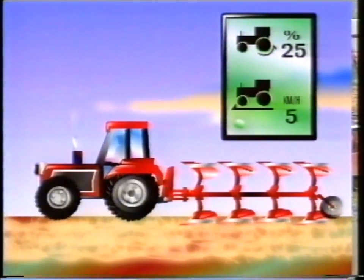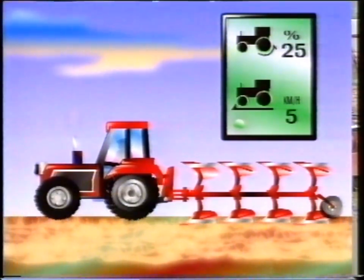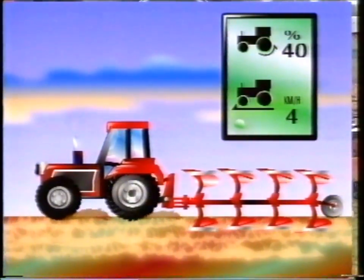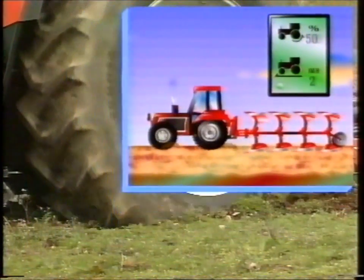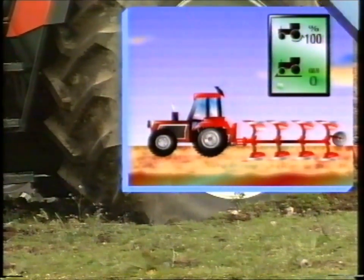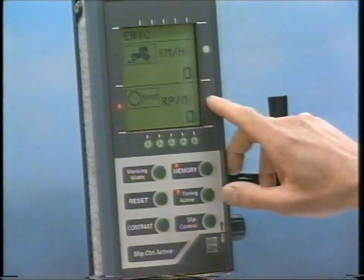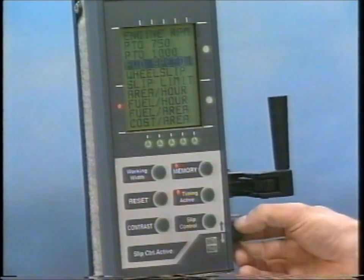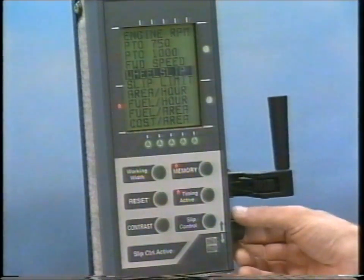First of all, we need to understand the dynamics of wheel slip. If left uncontrolled, wheel slip caused by a loss of grip reduces forward speed, thus reducing the draft force imposed by the implement on the tractor. In an effort to maintain the draft force, the ELC will instruct the linkage to lower the implement, further increasing wheel slip, and so on until the tractor finally comes to a halt.